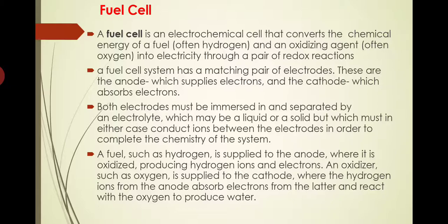in the case of a battery, once its charge is lost, whatever is fed inside is a permanent one. Once the chemical reactions are over, we have to either throw it away, or recharge the battery again. But in the case of a fuel cell, a continuous supply of fuel will be there. Out of that, some chemical reactions are taking place, and continuously we are getting electricity as the output power. So that is the main difference.